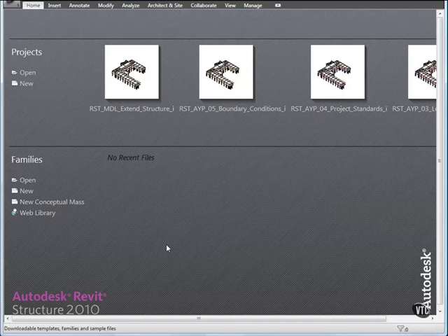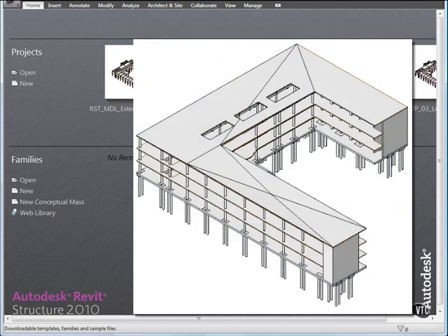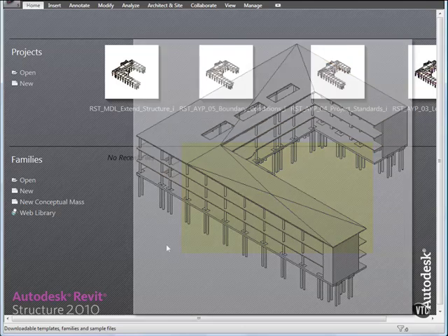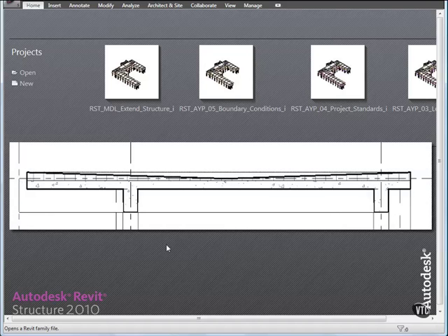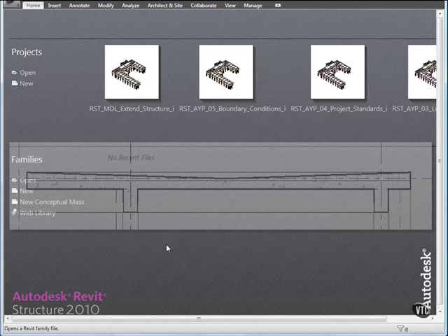In this lesson, you will add a slope to the roof slab of the structure to allow for roof drainage conditions. For this exercise, you will only modify one section of the roof. Also, you will add a new insulation layer. You will modify the slab construction to more accurately reflect the actual construction of the roof and the way the slope will be accommodated in the insulation of the roof.